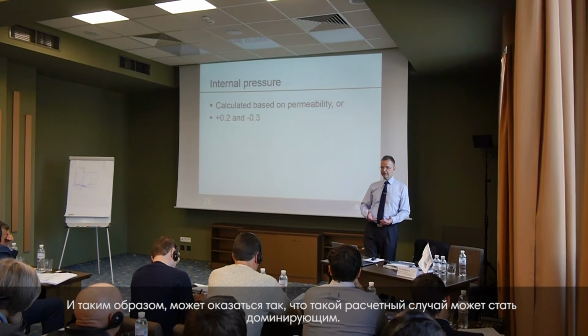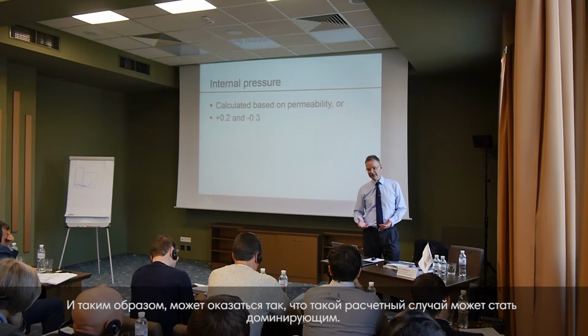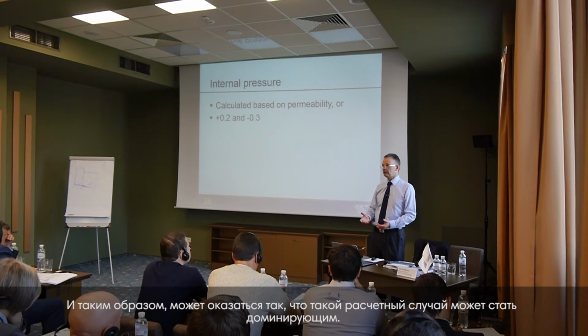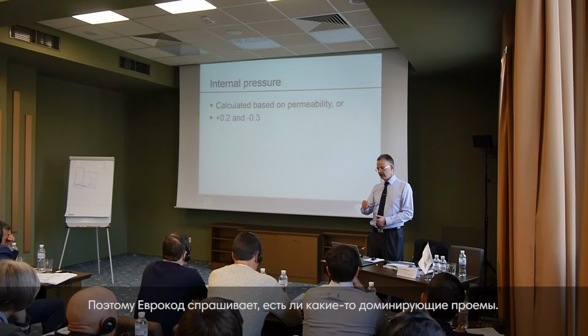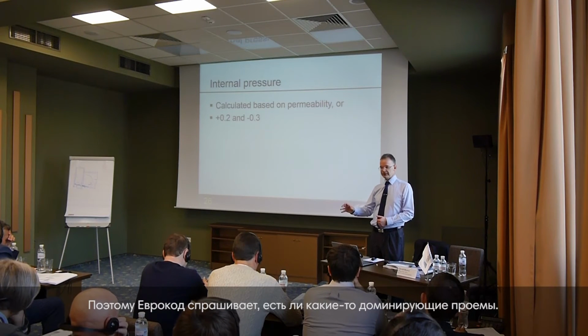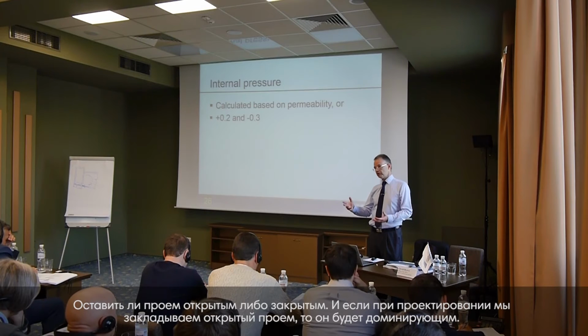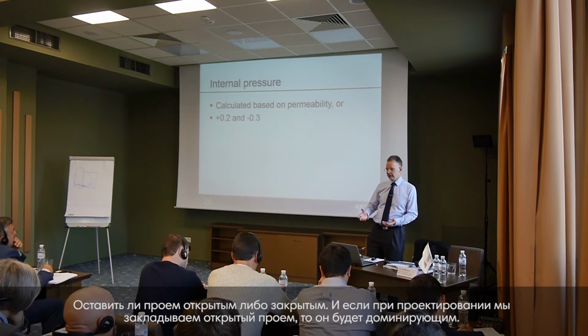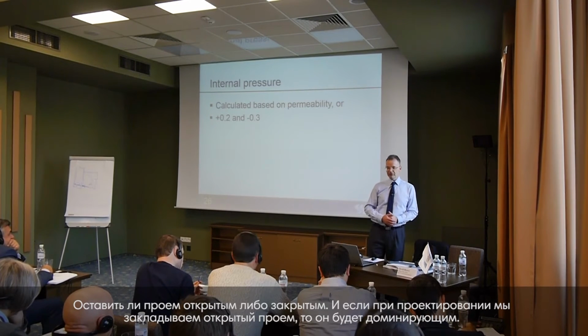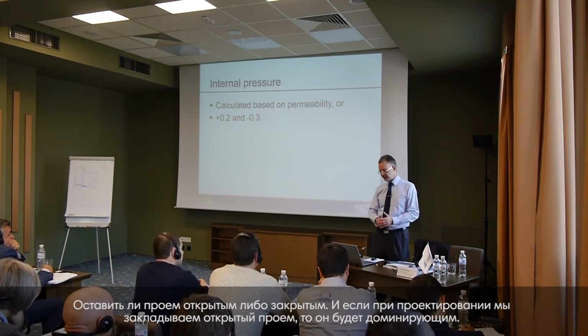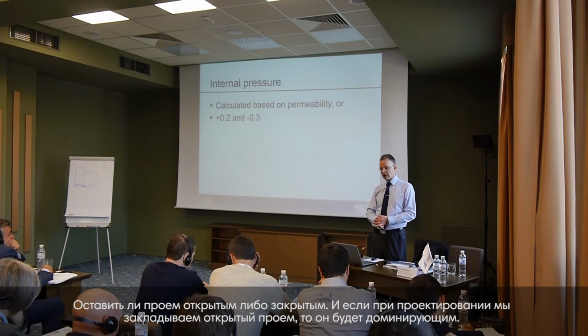So that may well turn out to be a dominant design case. So the phrase that the Eurocode uses is, are there any dominant openings? So a door or a window, or a door to let lorries into the building, for example, if that were open, that would be a dominant opening.